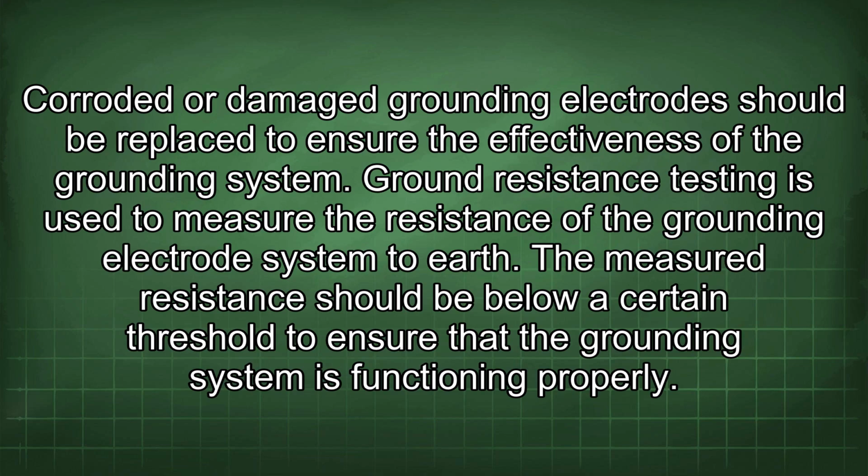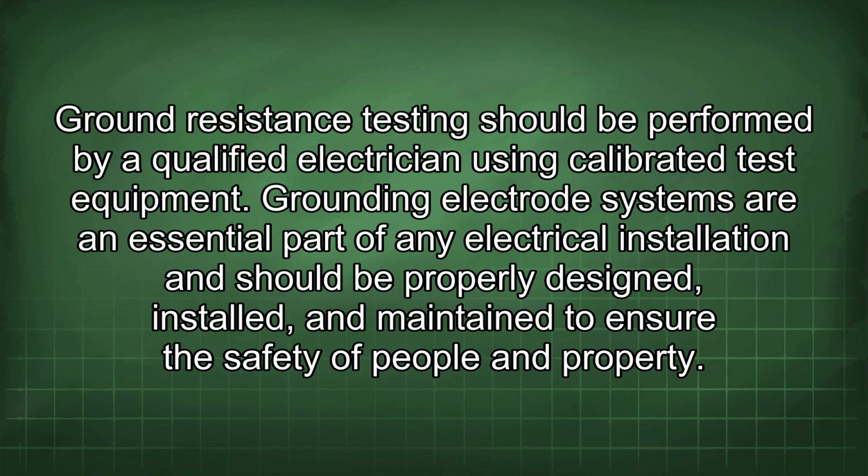Ground resistance testing is used to measure the resistance of the grounding electrode system to earth. The measured resistance should be below a certain threshold to ensure that the grounding system is functioning properly. Ground resistance testing should be performed by a qualified electrician using calibrated test equipment.